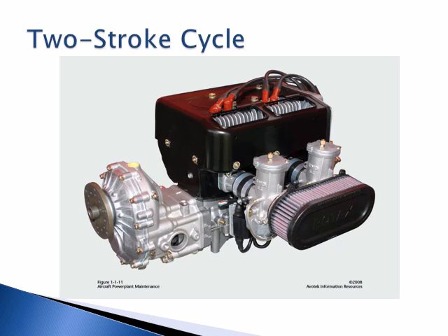What you're looking at is a typical two-stroke cycle aircraft engine, such as those used in ultralight and home-built aircraft. This compact Rotax engine showcases the simplicity and lightweight construction that make two-strokes desirable for specific aviation applications. Unlike four-stroke engines, this engine completes its power cycle in just one revolution, providing a higher power-to-weight ratio.